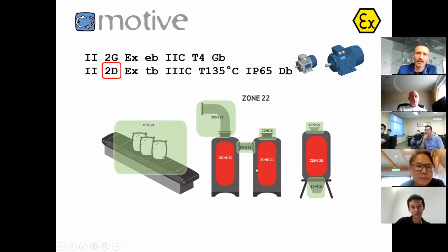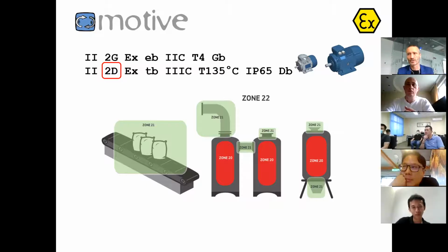So when you order a motor, a gearbox, a variable speed drive, and also some mechanical devices of any kind, an air blower, for instance, or a pump or something else, and this is conveying this combustible dust or this potentially explosive gas or liquid, that is category 2. Inside the tank is category 1. As you can imagine, inside the tank of benzene or the tank of a dust, you are not going to put any motor, any gearbox or something like that. That is why when we fulfill category 2, we are facing 99% of the market. In my personal working experience, we have never been requested category 1 by any client, probably because no one thought that he could put a motor inside the tank of a benzene.